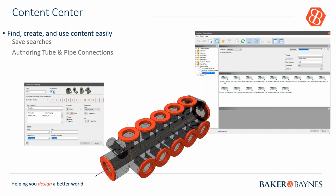Moving along to the content center enhancements in 2019.2, you find that there are multiple search enhancements that have been added to it. So advanced search and basic tab categories are now located in the quick search panel in the content center editor. So you can see on screen there's an advanced search tab in there. All right, the search query saves to the active search category, and the name of the search is the search values. To rename the saved search, you just have to click on the name in the browser itself.